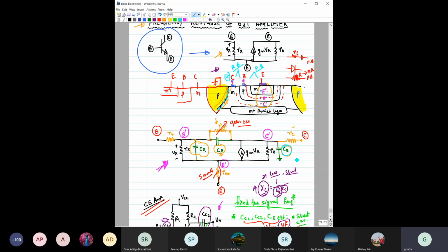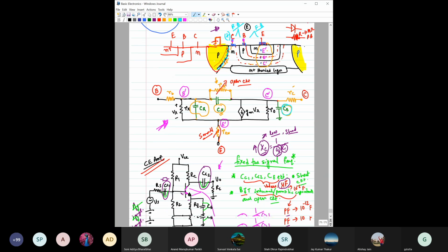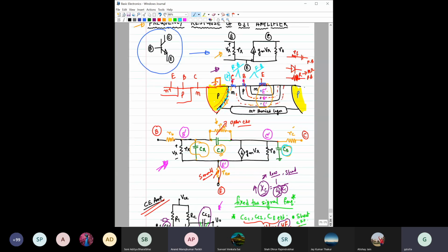I don't know which question you are referring to from here. No, sir. Now it is clear. Okay. So I did not understand why the gain falls at high frequencies. Because XC will keep on decreasing if we increase omega. So where is XC in the CE amplifier?